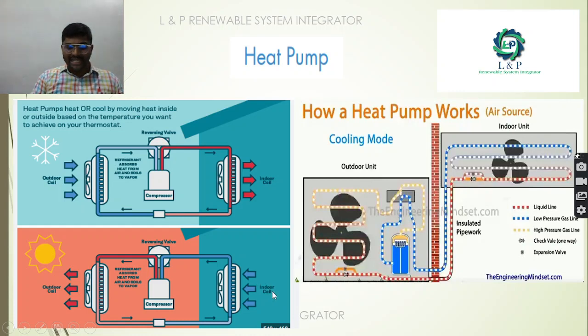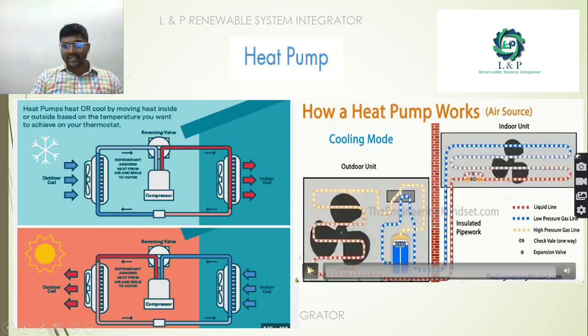So what it is doing, it is taking away the hot air from the room, and with the help of the compressors, it is sending it outside. As you can see here, this is a video which will demonstrate how the cooling mode is happening. We have a liquid line, a low pressure gas line, a high pressure gas line, a check valve, and we also have the expansion valves.